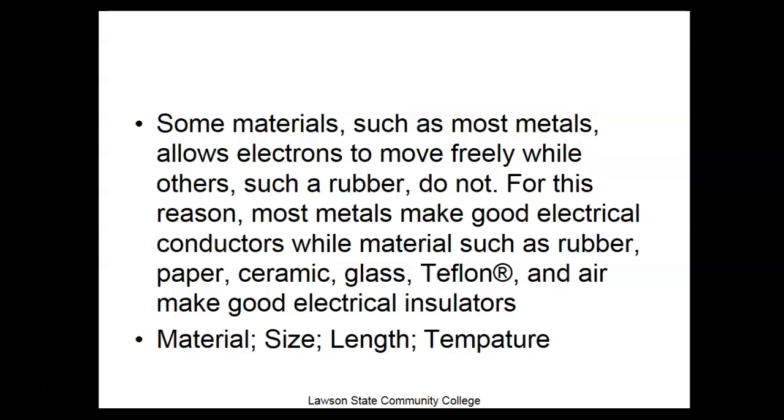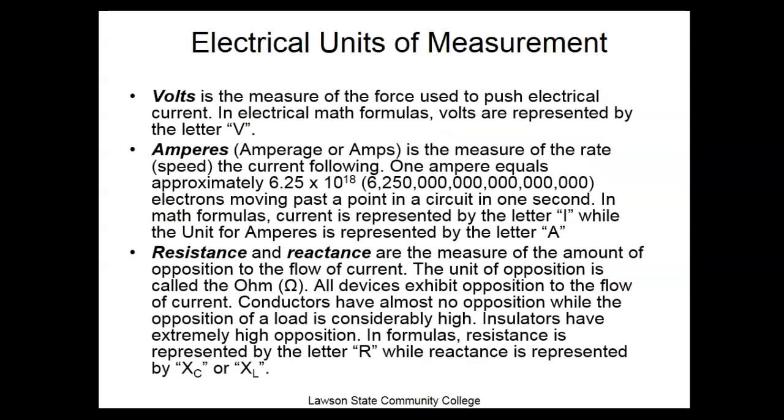What determines how much resistance your conductor has would be what it's made out of. So silver would have very little resistance per length. Then the physical size of the wires. So this is why the wires running from the downdrop of your transformer down to your house are a pretty good size, because they've got to handle a lot of current that supports your whole house. But then you get into your extension cords and stuff like that. Those have a lot smaller size, because they're not having to conduct as much current. Plus the length, and then the temperature. The temperature varies the opposition.